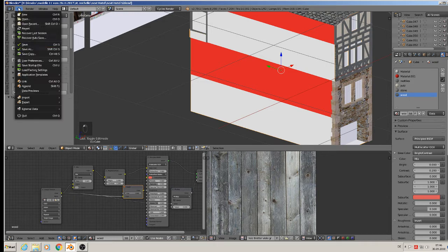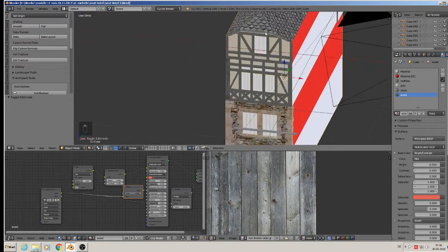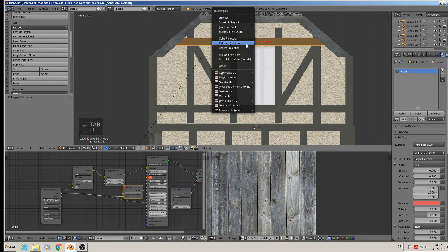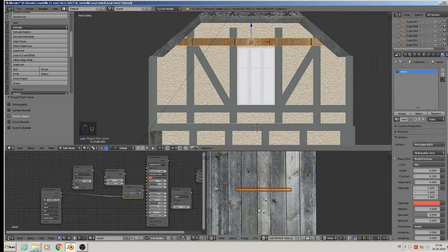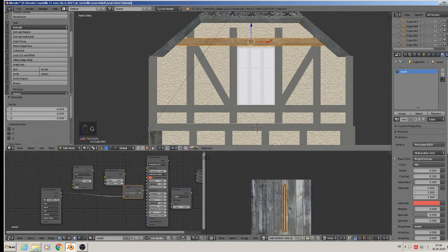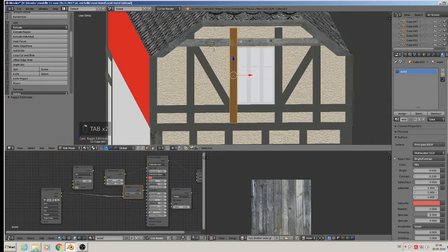Much work. So best we start. So from view, that is it. A to select all, rotate X 90 and scale up, grab, position. This one here should be longer at the top, so we get it and make it longer.